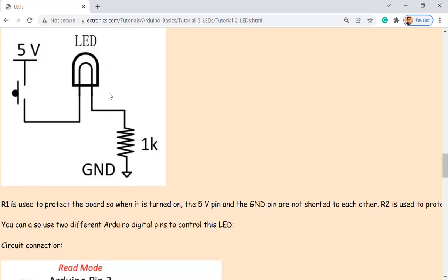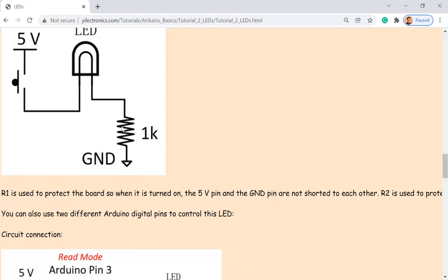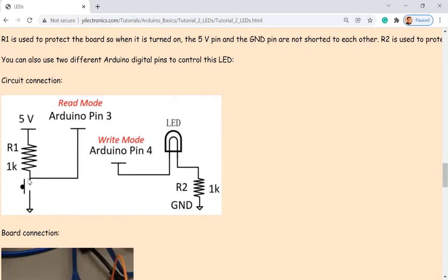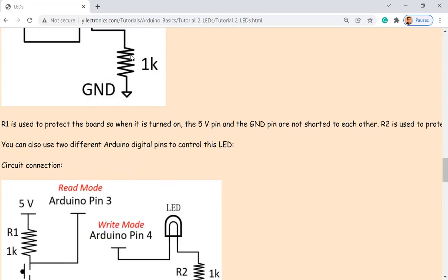Okay, same here. It's a little bit confusing. Why is this pulling? It's not pulling. This is a resistor. It's a passive component. Okay, it's just a name, right? This resistor is pulling this pin to the ground, and this resistor is pulling this pin to 5 volts. So this is a pull-up resistor. This is a pull-down resistor.